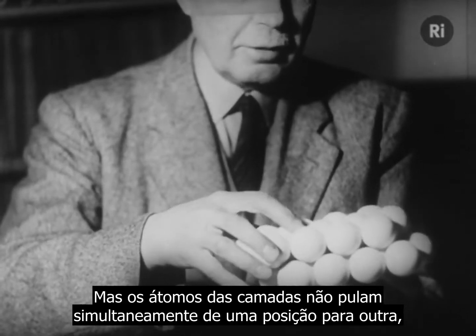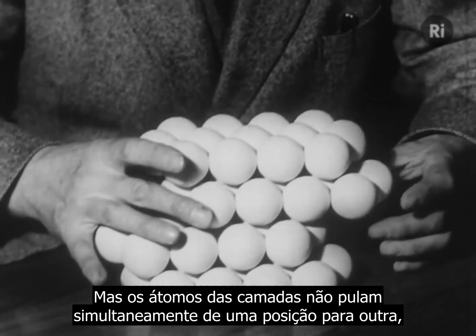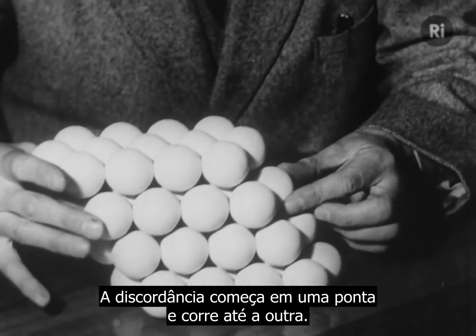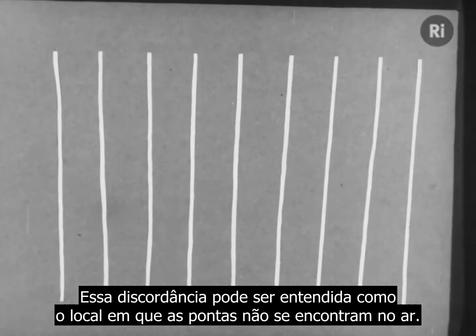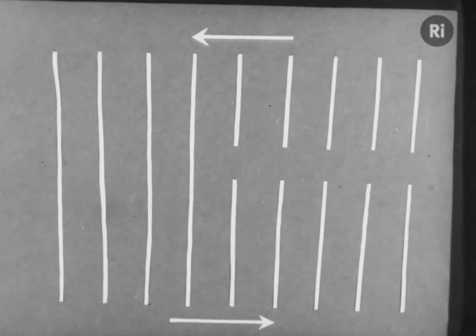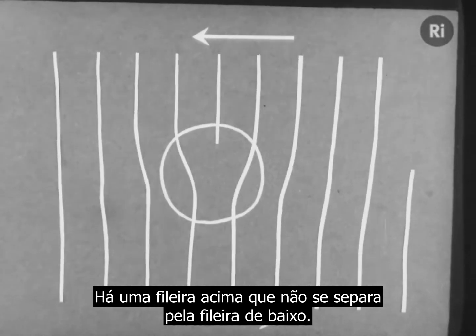But all the atoms in a sheet do not jump from one position of packing to the next simultaneously, as they're doing here. A dislocation starts at one end and runs to the other like a ladder in a stocking. A dislocation can be thought of as a place where slip is terminated in mid-air. There's a row above which is not partnered by a row below.